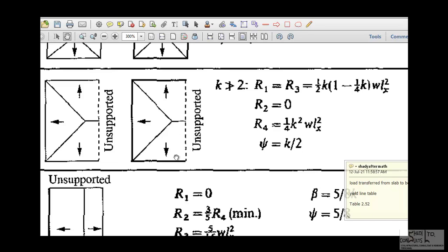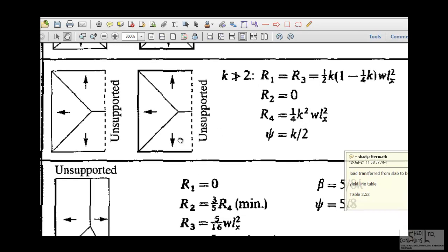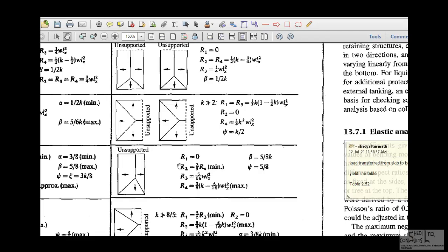The dead load transferred to the beams that he has omitted would invalidate his design results. It will invalidate the reactions at the support which he had used to size his foundations. It will invalidate the deflection criteria and so on, because the loadings were not applied correctly. Now, look at the loads that are supposed to be transferred to the beam. How is he supposed to idealize the loads?